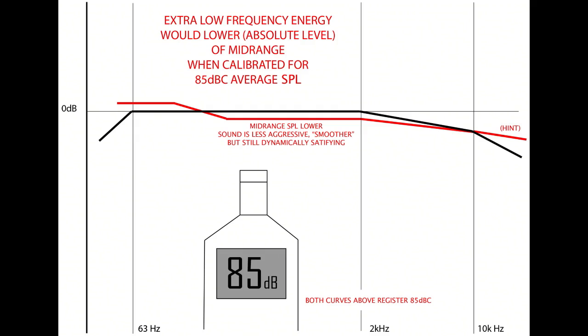So the X curve as it is, you end up with an emphasized mid-range because you're taking the top out and you haven't allowed for the natural sort of rise in the bottom that you would get from a typical enclosed space. And to my ears, both the pink noise and just the content sounds too mid-rangey, right? So I'm saying the reason, Scott, why you and I reacted that way was not because it was too loud. It wasn't, it was the mid-range level relative to 85 dB because of the target shape. It had too much mid-range content in it.